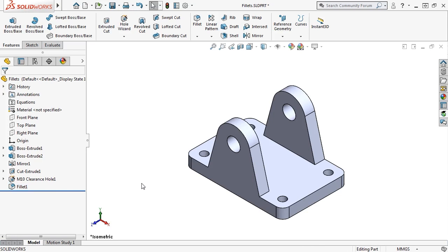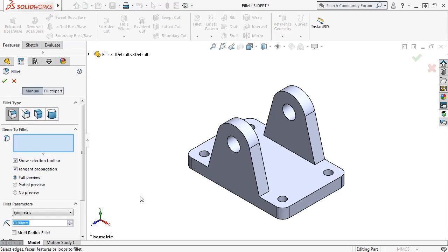The fillet is now added to the Feature Manager tree, so I can continue on with the next fillet feature. Now, instead of launching the fillet command from the Feature toolbar again, I'd like to show you a convenient shortcut. In cases where you want to launch a command that you are just working with, you can simply press the Enter key on the keyboard to have SOLIDWORKS relaunch the last command that you are working with. If you've worked with AutoCAD in the past, you'll probably find this shortcut familiar. Once the fillet feature is relaunched, we'll again select the constant radius fillet to create the smaller fillets.